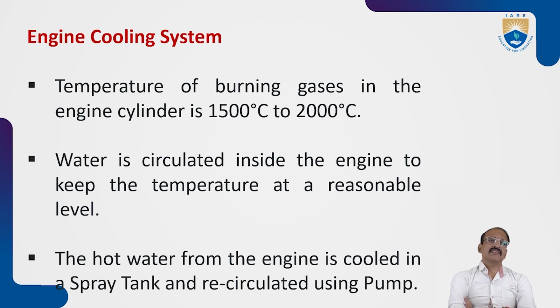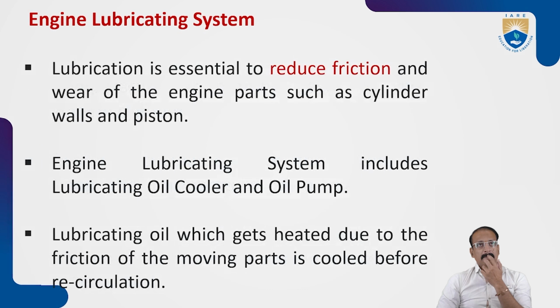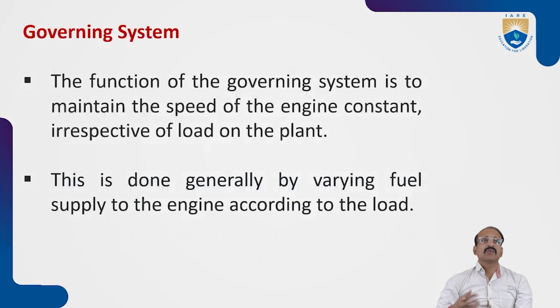The hot water from the engine is cooled in a spray tank and recirculated, and cool water is recirculated. Engine lubrication oil also will get heated, so we have to cool it and circulate it back. We have to recirculate that cool lubrication.